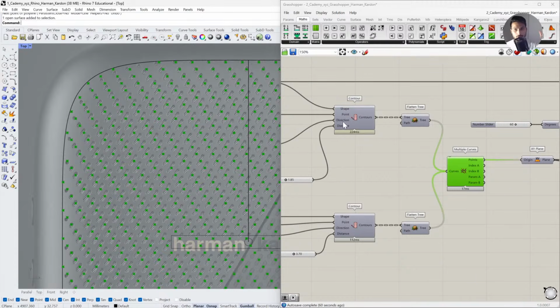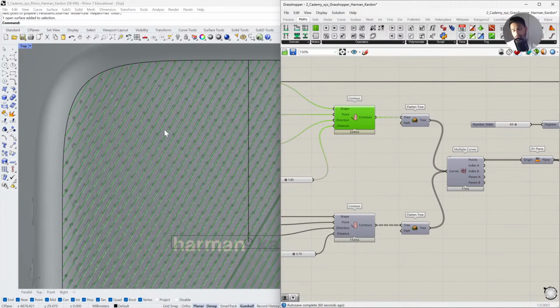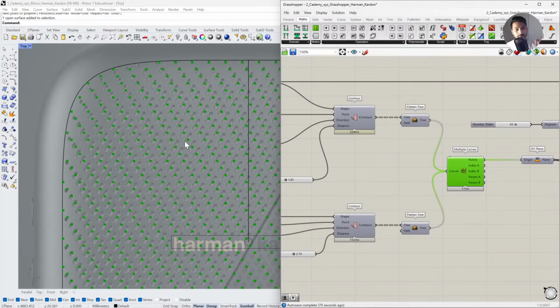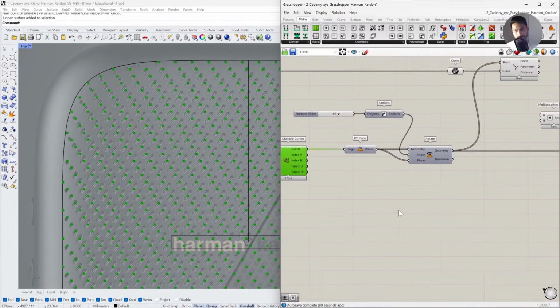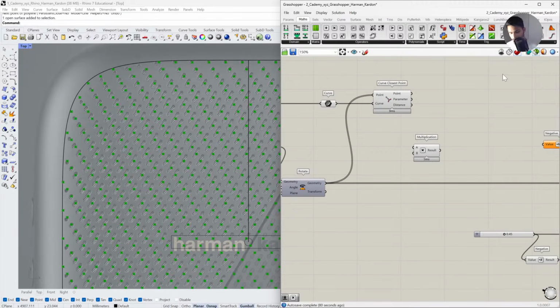And if you see the contour lines, all the contours have different length, so you have to divide them precisely by a certain amount so that the frames fall exactly on these places. So it's a lot easier to draw the curves and intersect them exactly where you need, rather than relying upon the divide command.